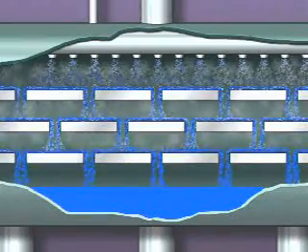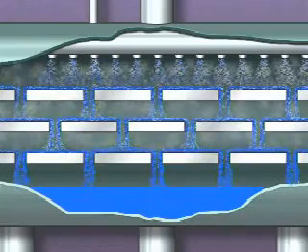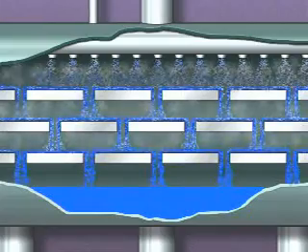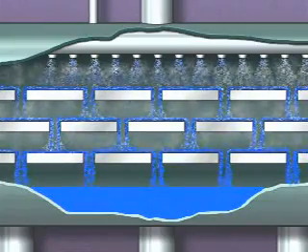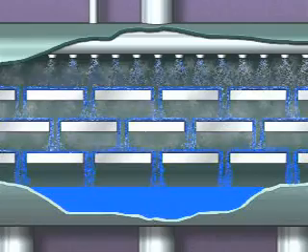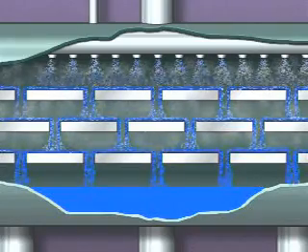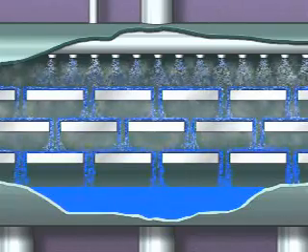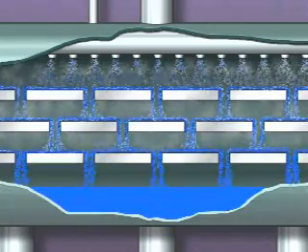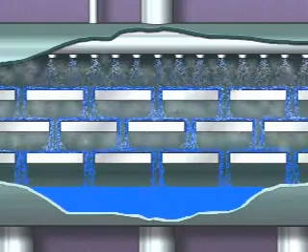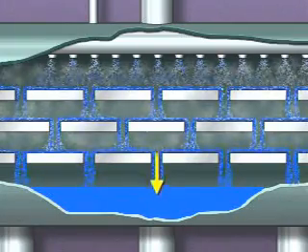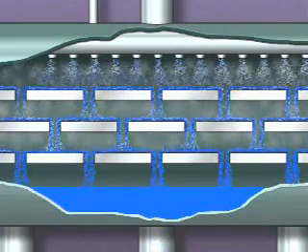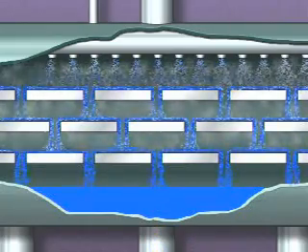As heat is transferred from the steam to the condensate, some of the steam condenses and some of the condensate is heated. This action strips or removes air and other non-condensable gases from the condensate. The heated and deaerated condensate that collects in the bottom of the heater is actually a mixture of condensate and drips from the heater. From the deaerator, the liquid will go to the hot surge tank for storage. From there, it will go on through the condensate and feed water system to the boiler.